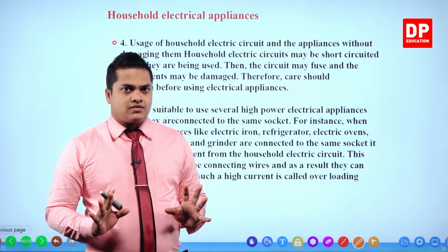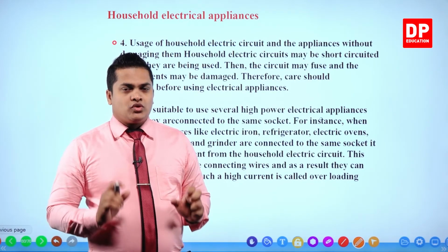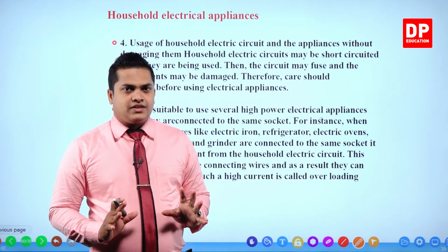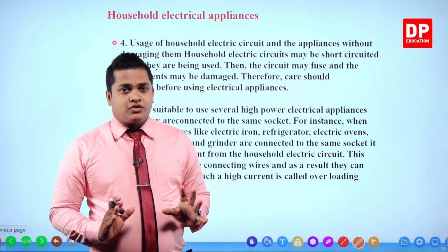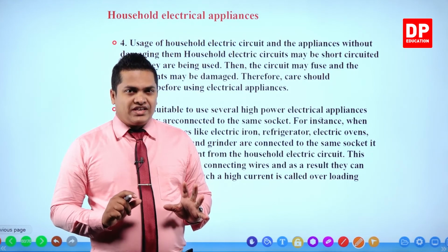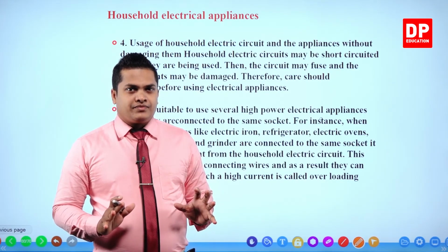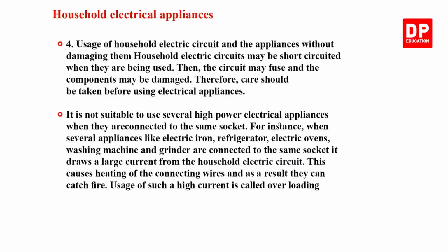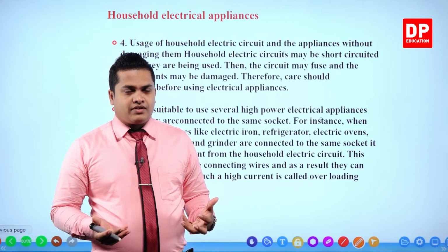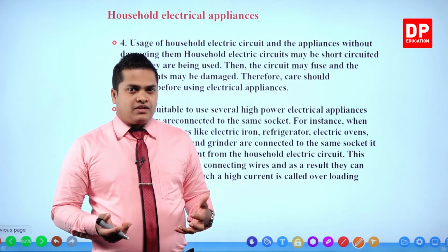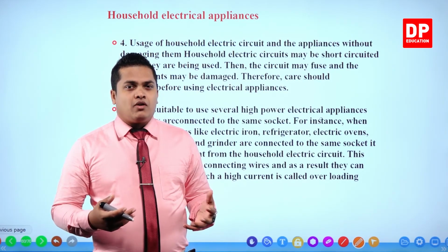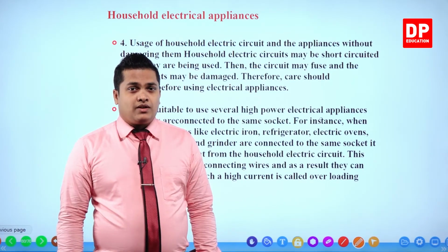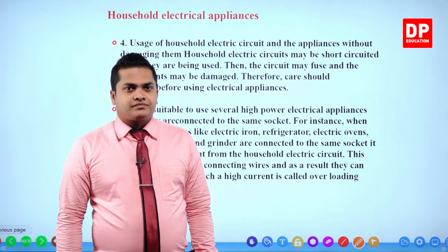Don't use multi-plugs for those things, because they are going to draw a large amount of electric current, as the power consumption is very high. So it's wise to use them separately, right? If you are going to use these things, which draw a high amount of current, there might be a possibility that the wires may burn out in the multi-plug and sometimes in the electrical appliance as well upon heating, right?